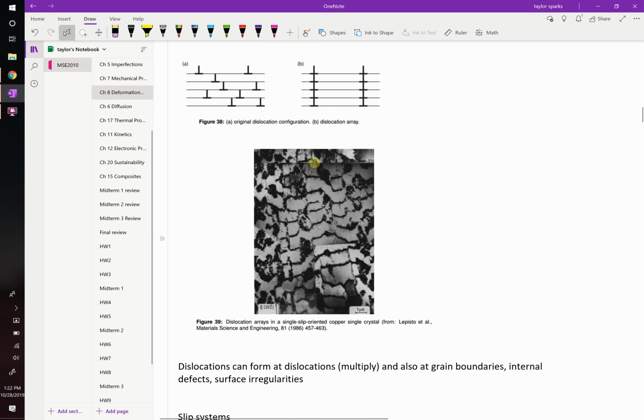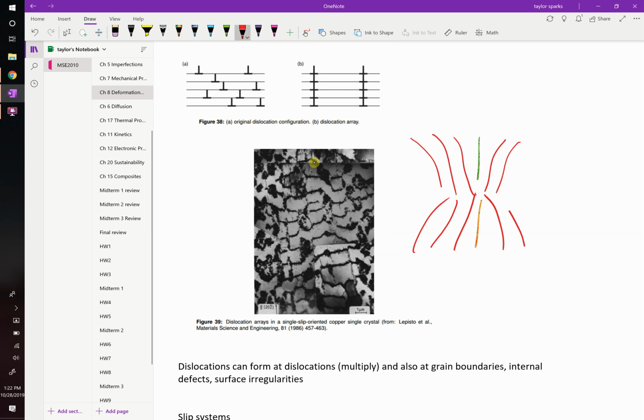So you're talking about, you've got this extra half row of atoms here. So you had this extra half row there, but you had the same thing happening on the other side. So would they create a vacancy here? No. You'd probably get an atom diffusing there to fill that vacancy, because as soon as you put one more atom here, as you fill that spot, then you have a perfect lattice again. All that strain can be relieved if you just get an atom there. Right now it has basically a vacancy there. Oh, it would have to diffuse there.